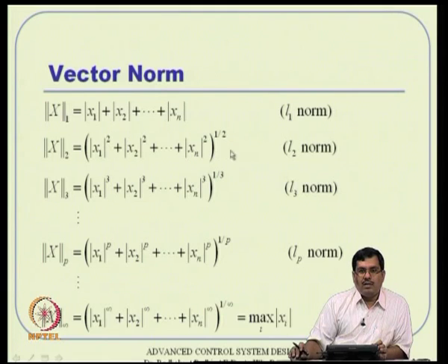So, most of the time we will deal with the second norm, but you will see that all LQR theory, quadratic things, and then this Kalman filter, all these things we will talk about as H2 sort of an idea. Sometimes these are called H2 norms also. H comes from Hardy space and all that actually. I will not go too much into that. And then either we deal heavily with the 2 norm, or sometimes we like to deal with the maximum quantity of the noise and things like that. Your system has to be stable for the maximum noise magnitude that you expect, noise frequency and amplitude, all that. That concept is the H infinity concept.